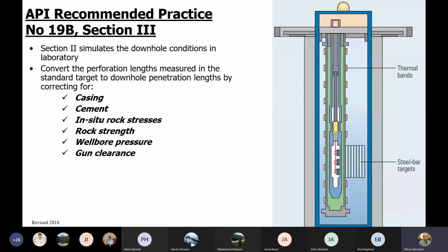Section 3 test is used to evaluate perforating system performance at elevated temperatures, and this test characterizes a system's function, reliability, and performance degradation at elevated temperature. These tests are typically conducted in pairs, one at elevated temperature and a second test at ambient temperature, to use as a benchmark. May incorporate elevated pressure to further verify the operational rating of the system.